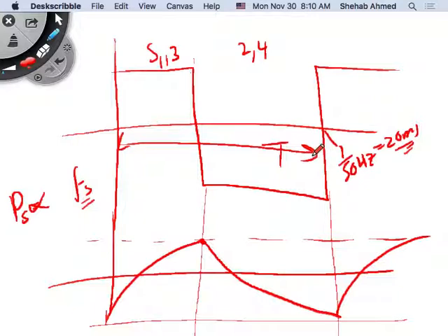The idea of switching at fundamental frequency, once every fundamental period, is a nice thing. So there's a family of converters that was developed to make use of that. And then there was a family of converters developed to try not to make use of that, and to switch multiple times to increase the switching frequency. So there are 2 main families of inverters that we will discuss.